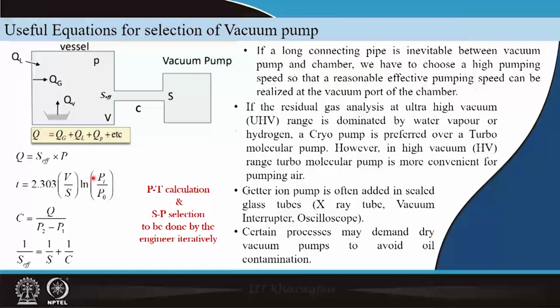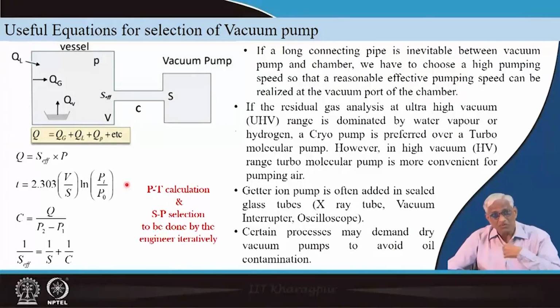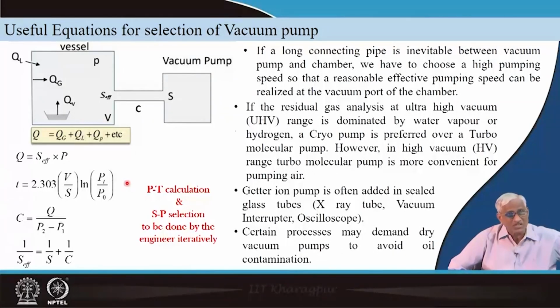Instead of 10 minutes, let it take half an hour. Once it comes, afterwards it is a load that is being pulled by the vacuum, equilibrium pressure, that runs for days together. So, how does it matter, initially 1 hour takes 2 hours. So, this equation is very important in the semiconductor industry, particularly for load lock chambers, because if you can put the next silicon wafer faster, you will get faster chip production, okay.